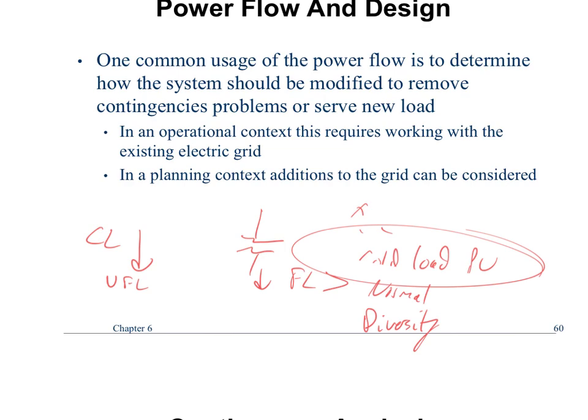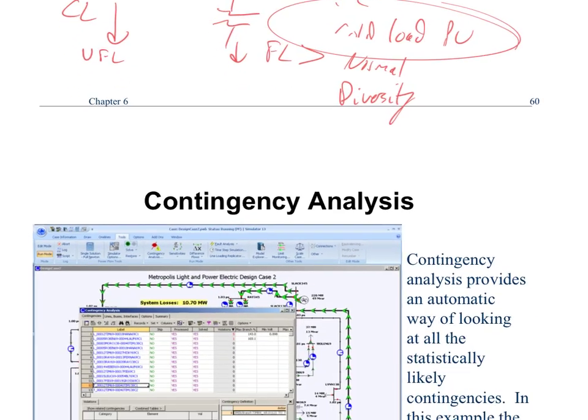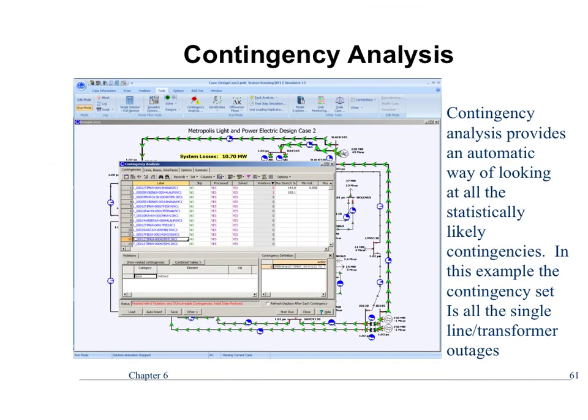With the inrush current for starting furnaces in the winter, they must size all that fusing and everything. No, because the inrush currents on furnaces... my furnace I think has a half horsepower motor. So even if it was 7 times locked rotor on a half horsepower, that might be 20 amps. Even if half the state lost power, it's only going to get that inrush for a brief moment in time. So the only thing we'd have to worry about would be any instantaneous elements. Most of the other stuff, the short time elements, wouldn't trip on that.